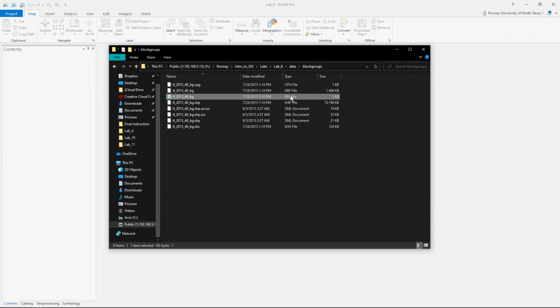I've gone on for 2 minutes now about what you should do. It's not very difficult. Usually the problem is that people use the wrong tool and they'll use define projection, or they can't locate their PRJ file because they didn't change the default folder, or they can't locate it on their computer.